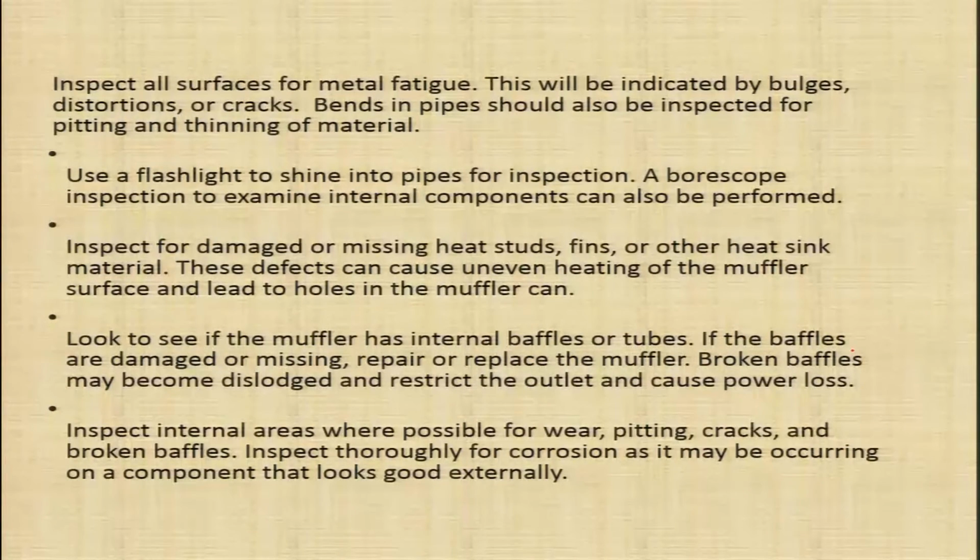As we have seen earlier, if your exhaust outlet is blocked, then there will be excessive exhaust back pressure and finally it may result in power loss. So, if the baffles are broken in the muffler, they will become dislodged and restrict the outlet and cause power loss. Inspect internal areas where possible for wear, pitting, cracks and broken baffles.